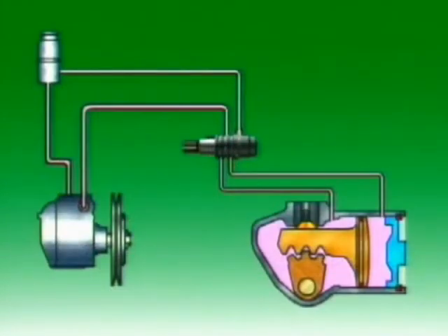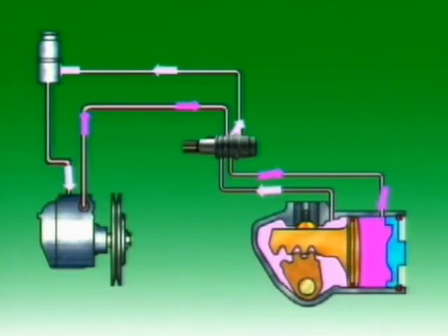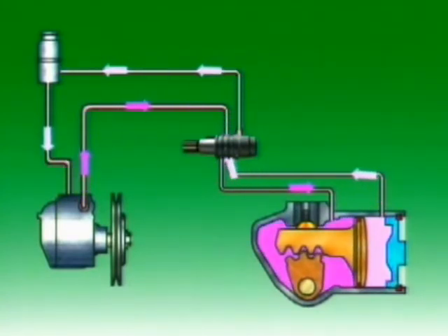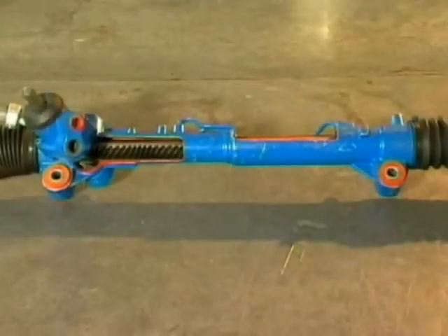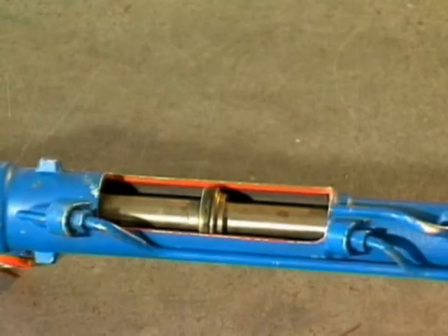In a worm and roller steering box, the piston slides in a cylinder in the casing. It has an extension formed on one side with teeth which engage teeth on the pitman shaft. Pressure applied to either side of the piston produces a force, which is transferred through the teeth to help turn the pitman shaft. In a rack and pinion steering gear, the piston is formed centrally on the steering rack, and the rack housing provides the working cylinder.